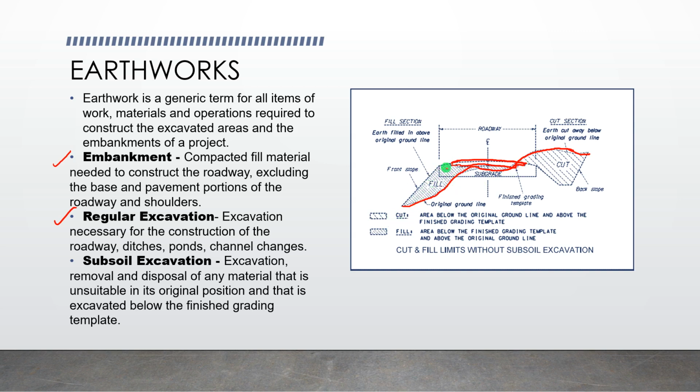So for it to be safe, we should have an embankment here, and depending on the specifications in our country, that is allowed for the slope needed on this side, we shall follow that. But usually we have a horizontal of 1.5 to 1 vertical.